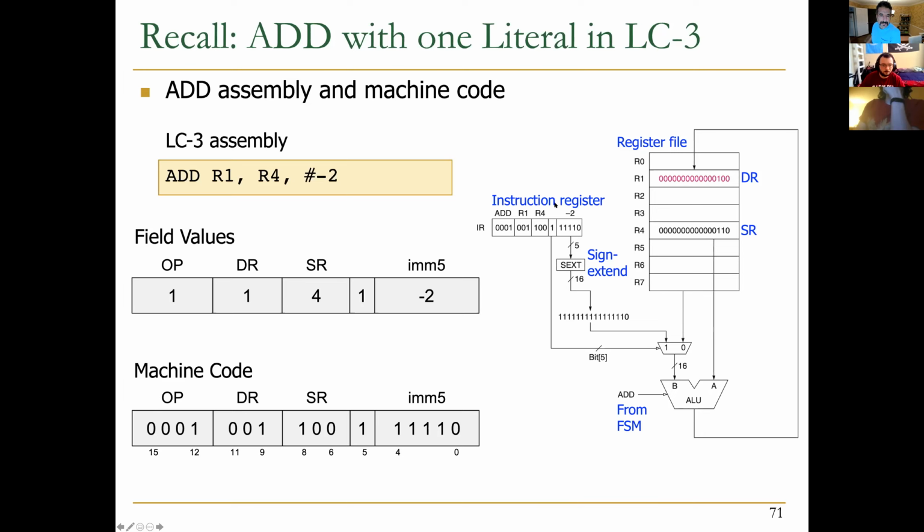So you had an opcode, you had a destination register, you had a source register, and depending on this bit, if it was 1, you had an immediate, or you had the second operand that you could read from this register file. So you have the same elements. You have an ALU. You have some control signals that come from a finite state machine that we will discuss later on. But essentially, it's a very similar microarchitecture with slight differences, and this difference comes from this particular encoding.